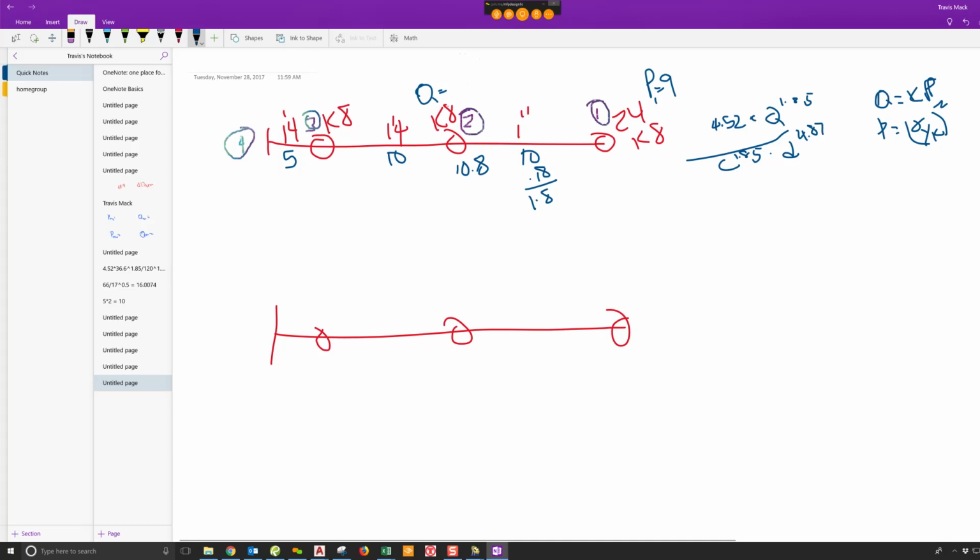Okay, so did you get this 26.3? Okay, so now we got to find the flow going through this piece of pipe here. So the total flow is 50.3, right? As I just added the two together. And now we need to find the friction loss in this section of pipe.